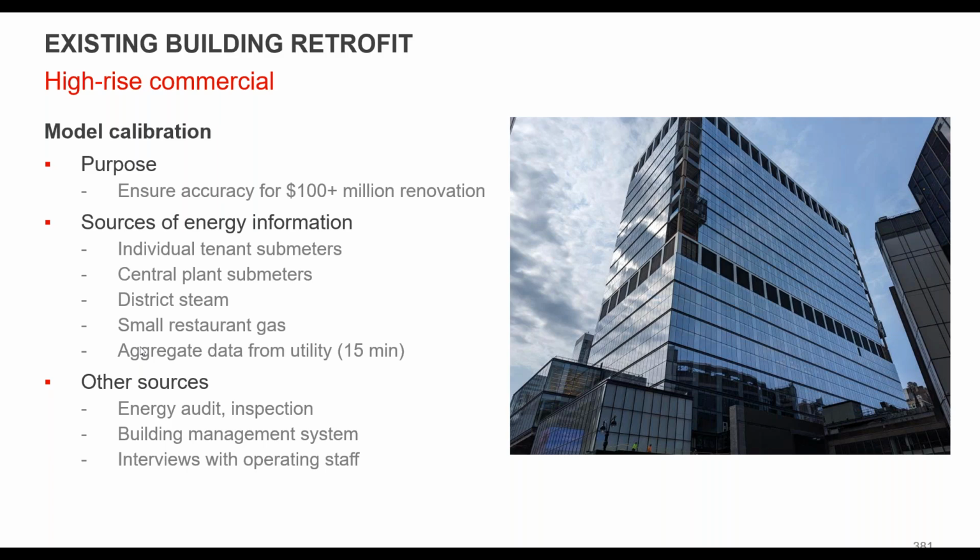So it's a good question, though. And then Jose was asking another one. For an existing building constructed 30 to 50 years ago, are there resources for this kind of data? Again, CBEX has some of this data. They'll have assemblies and things. A lot of times you'll have to go just to the building code and the energy code that was applicable for when the building was built to kind of get a better idea of those kinds of things in terms of envelope, or you're going to look at the building. I'd say a lot of times you need to go look at the building.